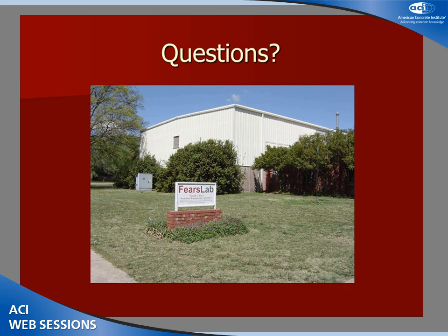Yes? So, would you expect any difference in the expansive characteristics if your restraint condition changes from uniaxial to multi-axial? That's an additional further field of investigation moving forward to evaluate how uniaxial restraint influences expansion in other axes, and then from there to move on to how multi-axial restraint influences multi-axial behavior. And that's something that's easier to investigate now because of the Geocon vibrating wire capabilities that we have. It's something that wouldn't have been possible previously.